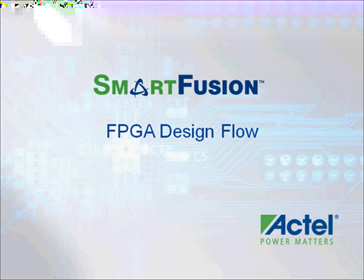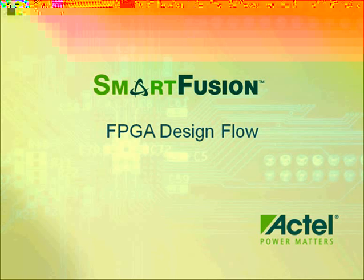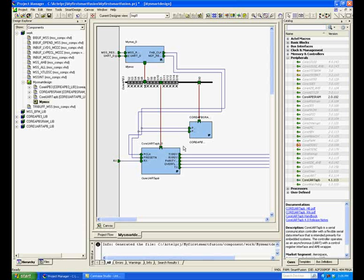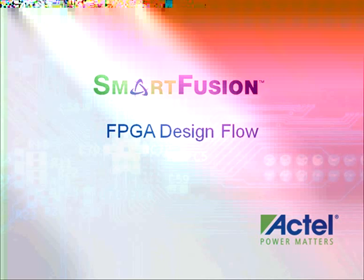At this point, the logic design is complete. Right-click the Smart Design canvas and click Generate Design. This process converts the design into design rule checked and synthesis ready HDL code. From this point, you will follow the traditional FPGA design flow.